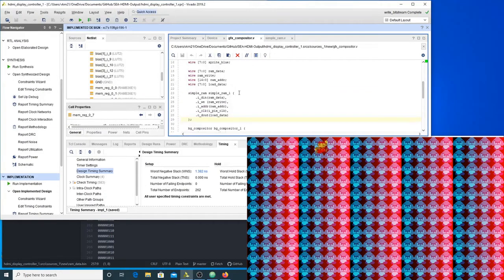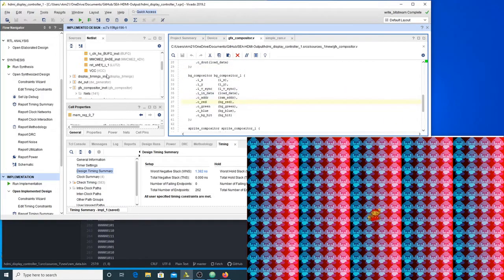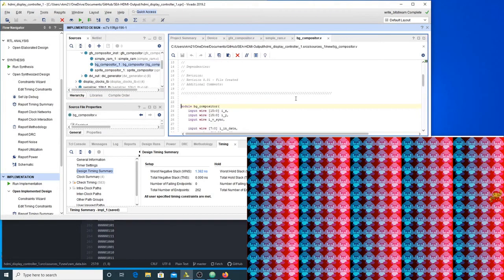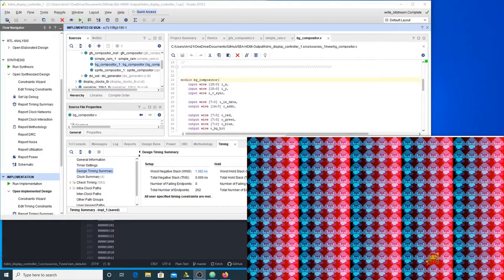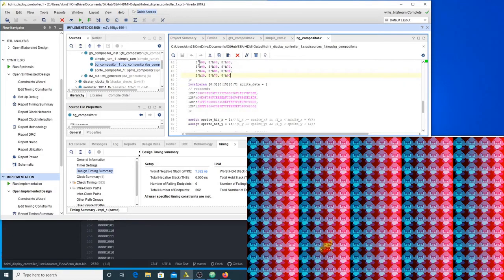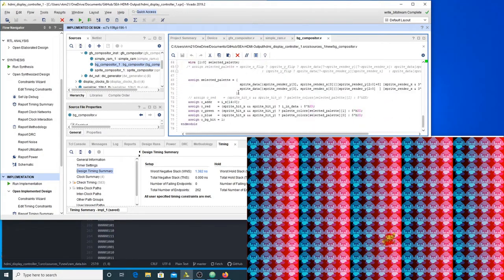And so then I wanted something to be able to do with those values, something easy to start. So all I did for now is I took our background compositor and hooked it into the RAM. In our background compositor, which remember shows our Goomba pattern there, instead of using these color palette colors that we used before with the Goombas, we pretty much kept those the same, but I replaced the red color that was defined from the palette.